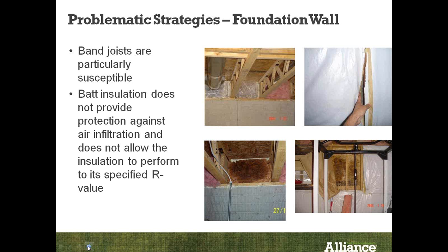The other areas that we see a lot of is when insulation is applied to band joist areas, where typically they're insulated, but we're allowing the moisture-laden air to get in contact with a cold surface. In this case, on the bottom left, we're seeing an OSB band area. That actual band area was insulated, but it was covered. You'll see fiberglass bats that were stuffed between these open web joists. It was meeting the R value of that climate zone, but the fiberglass bat that was stuffed in there actually cooled off that OSB band surface to the dew point temperature. The issue we saw here was that fiberglass is not an impermeable insulation. It was a vapor permeable insulation, so it was still allowing vapor to diffuse through the bat and condense on that cold surface.